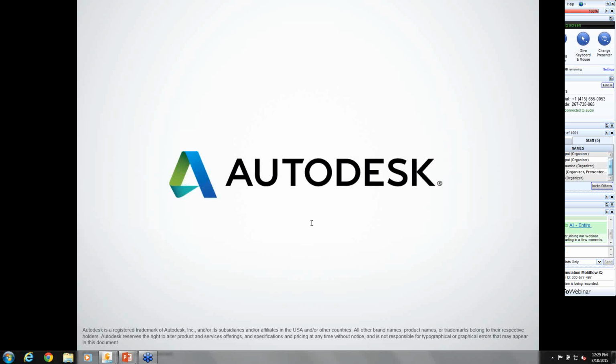If I set my 3D model to be just 6 layers or just 8 layers through the thickness, you're reducing the resolution through the thickness, and the opportunity there is to get something that will run in almost the same time or quicker than the 2.5D mesh, but with less accuracy through the thickness. So what I did was an apples-to-apples comparison. It is possible to get faster run times out of 3D, again, by reducing accuracy. It would be very similar to taking your dual domain model and meshing it coarser and telling me that it could run faster. It's the same type of idea.